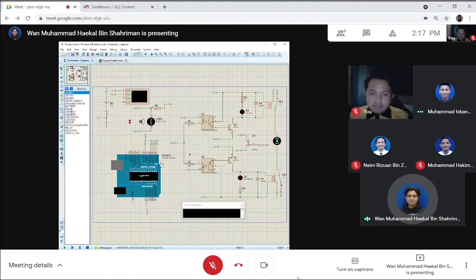There is an inbuilt analog to digital converter, ADC, present in the Arduino Uno. With this feature, the output of the LDR, which is an analog signal, is converted to a digital signal, and the Arduino will analyze it and generate the PWM, pulse width modulation, signal in the PWM pins. The output signal via PWM pins will be an analog signal acquired as digital signal from the Arduino, and it uses the duty cycle of the digital wave to generate the consequent analog value for the signal.